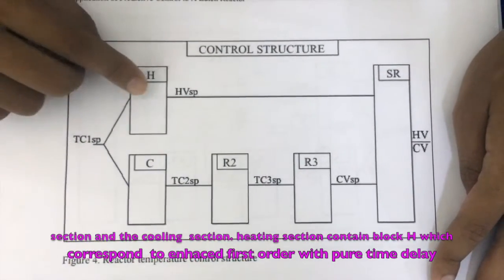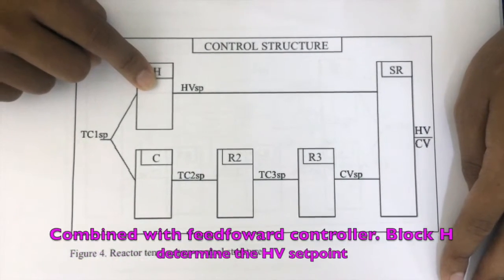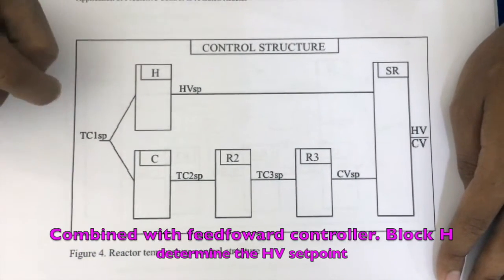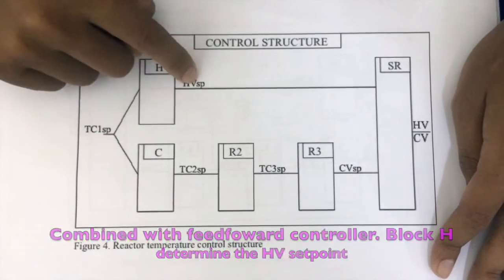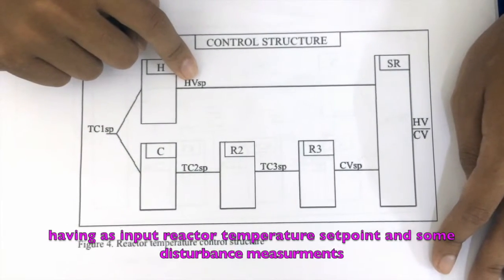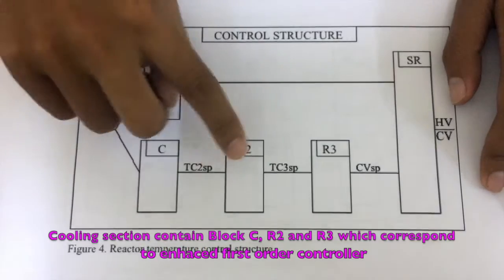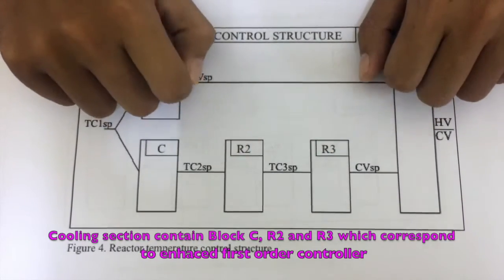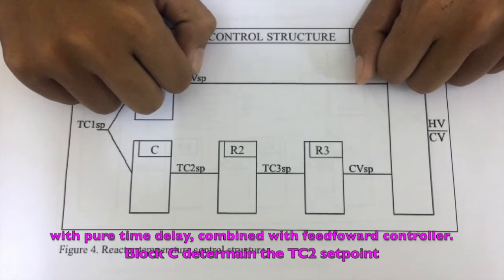The heating section contains block H, which corresponds to an enhanced first order controller with pure time delay combined with the feed-forward controller. Block H determines the HV set point, having as input the temperature set point and some disturbance measurement. The cooling section contains blocks C, R2 and R3, which correspond to an enhanced first order controller with pure time delay combined with feed-forward controller.